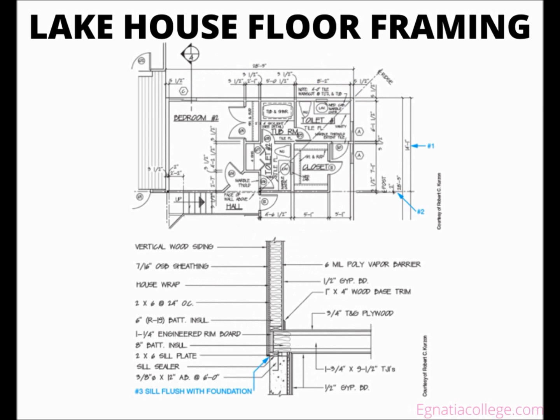The bearing support for the inner ends of some of the joists in the lake house is the structural steel and LVL beam core, detail 5-6. This core consists of 4 1.5-inch square steel posts with LVL beams and steel channel beams. The positions of the posts are shown on all plan views of the house. The C8x11.5 steel acts as a beam to support the floor in bedroom number 2.